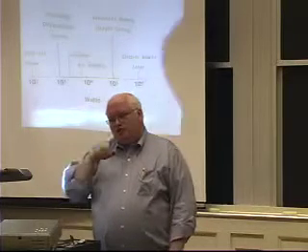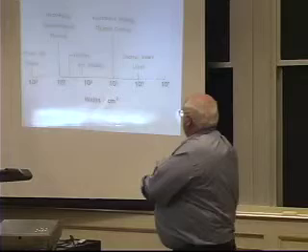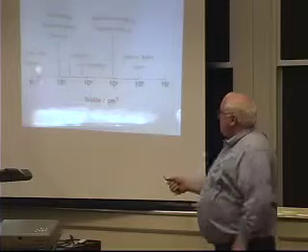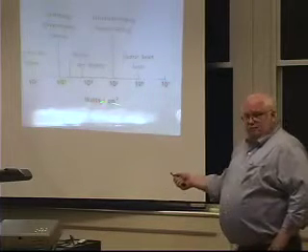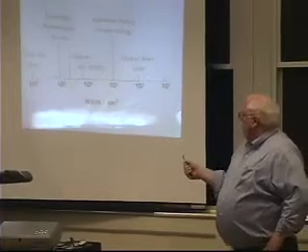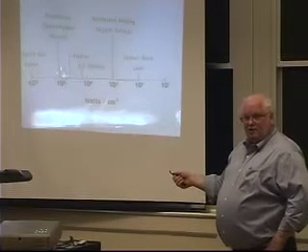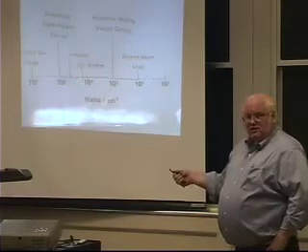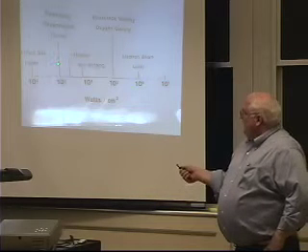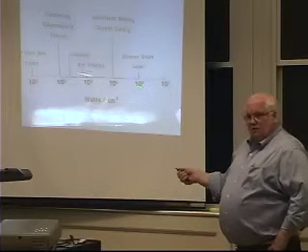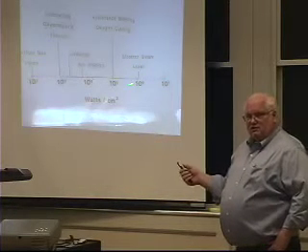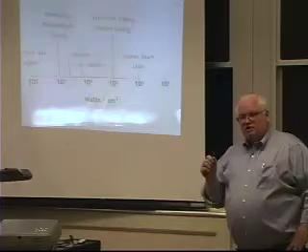It turns out when you're going at very high speeds, and you are going at high speeds here, remember when I put this up, I talked about speed of welding, and it goes up to 1,000 inches a second over here, and only one inch in 10 seconds over here. The speed goes almost like the square of these heat intensities. Higher heat intensities means you go faster.